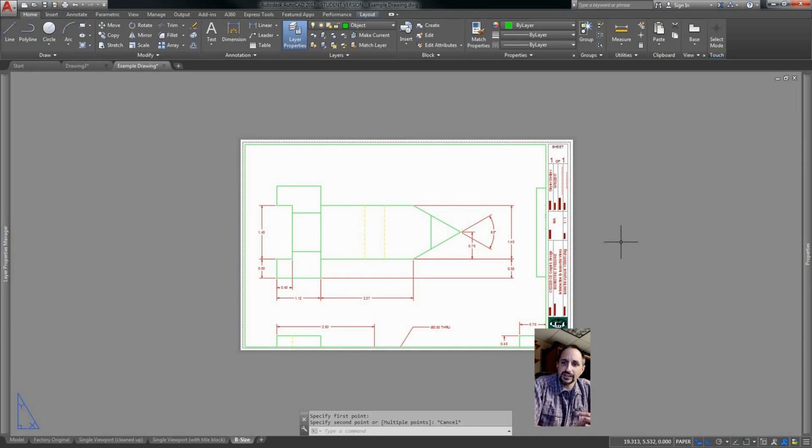Lastly, and I'll say it again, you must set your scale for each viewport. If your scale reads, say, 0.4983125, for example, that's not good. Your scale should read something like 1 to 1, 1 to 4, 1/4 inch equals a foot, etc. In other words, you must use a common engineering or architectural scale.